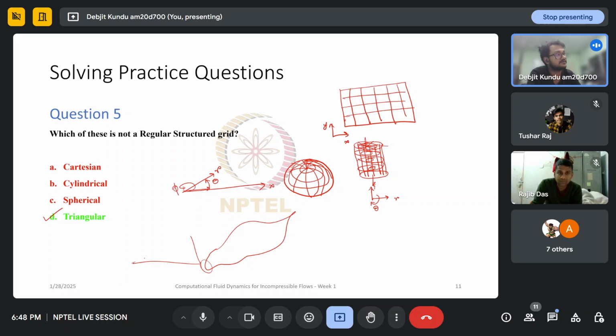My drawing skills are amazing. So I'm zooming out this portion over here. Let's say I have a curve like this. I can approximate this by using a triangular grid. I take points like this and make one triangle. I make another triangle. You can already see that I'm missing out on this curvature. This is the true one, and this is what I'm assuming.